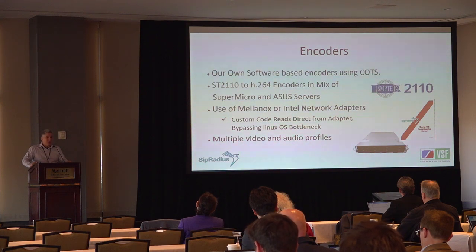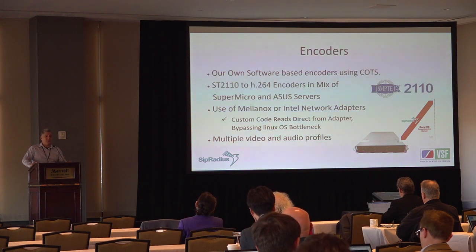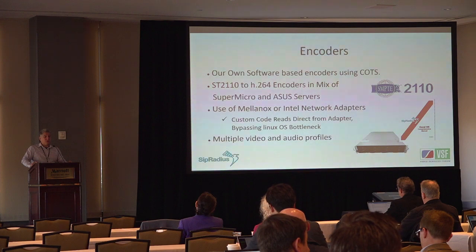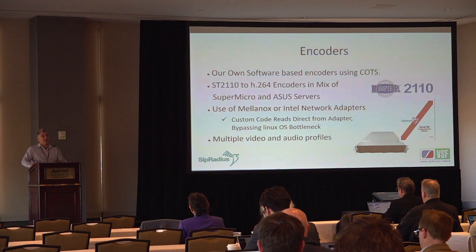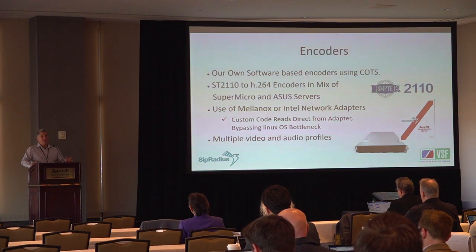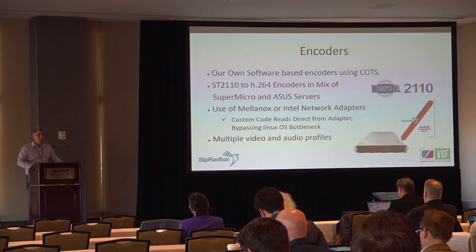Each of our encoders can handle 20 incoming 2110 streams, and we can produce two H.264 video tracks for each at different resolutions and bit rates. We can produce 32 audio tracks on each stream, because we create 16 AAC audio tracks and 16 Opus tracks from the original uncompressed audio tracks.